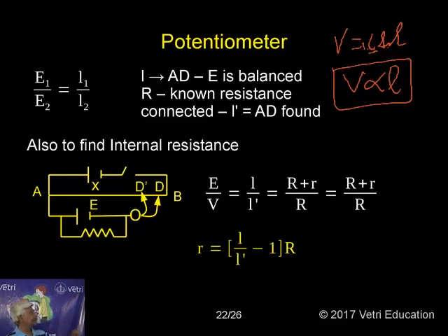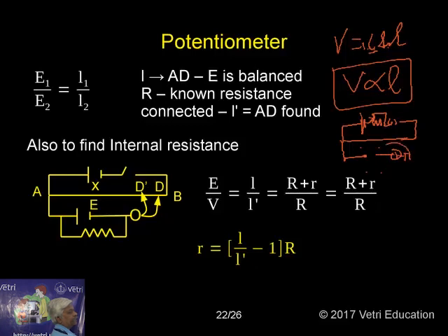That is the principle. How to compare the EMF of two given cells? The same circuit, we know the previous thing, the primary circuit is always there. It is connected to a battery, a rheostat, and a key. Here we have to connect the potential difference, that is, V is equal to IRL principle. Here we have to take the DPDT switch, the 6-way key, from which the galvanometer, high resistance, and jockey are connected, and from which the cell to be compared is connected.